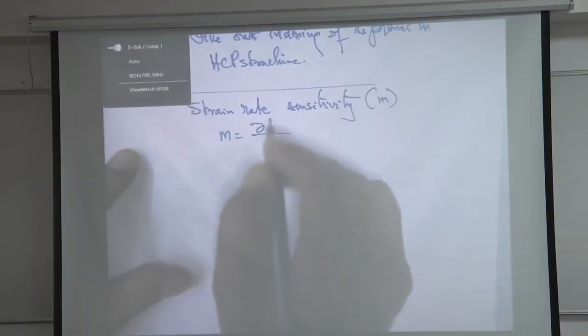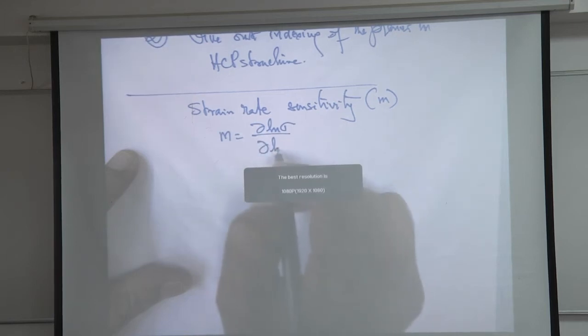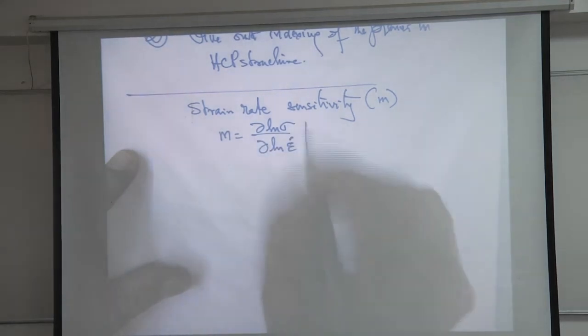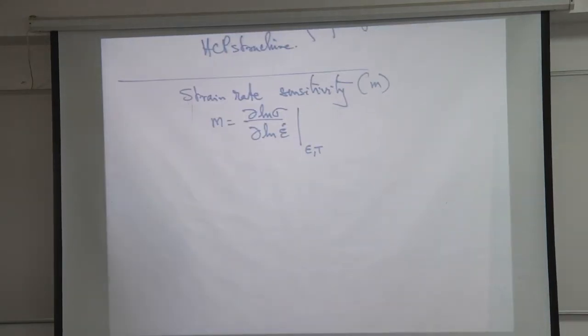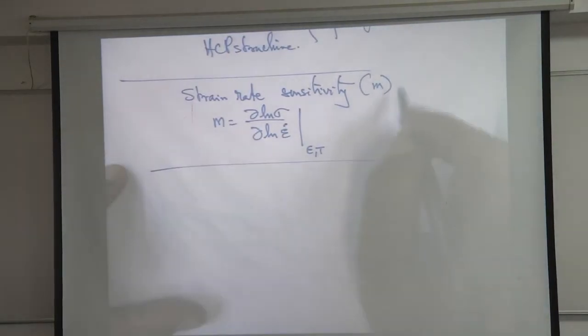It is the derivative of log sigma with respect to log epsilon dot, at constant strain and temperature. Okay, that is your strain rate sensitivity parameter.